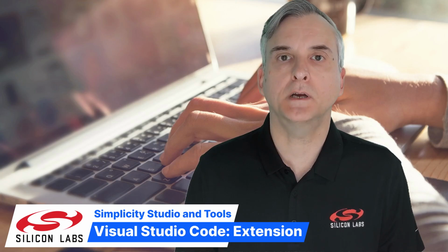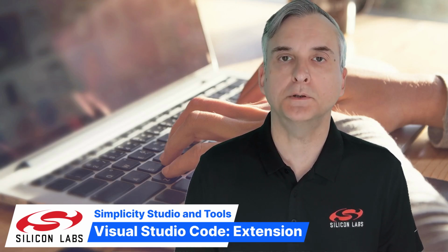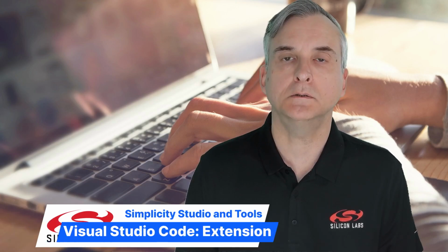In previous videos in this Simplicity Studio series, I showed you how to create the Bluetooth Blinky example application, update its Bluetooth GATT database, and add a button driver using software components. In this video, I'll show you how to output the project so it can be used in other IDEs, if you prefer them to Simplicity Studio, and I'll be focusing on the Visual Studio Code IDE from Microsoft.